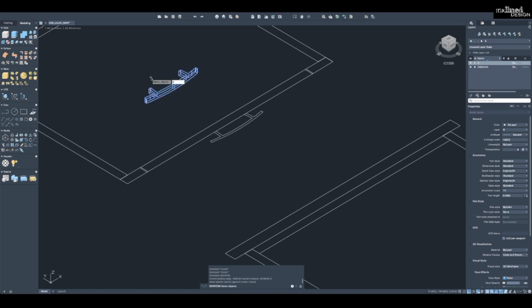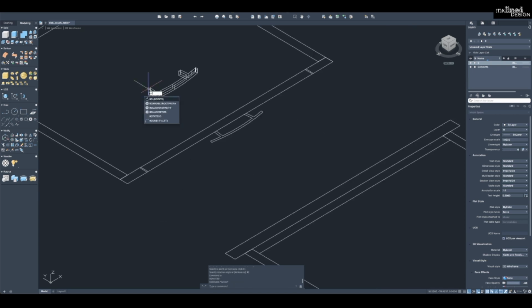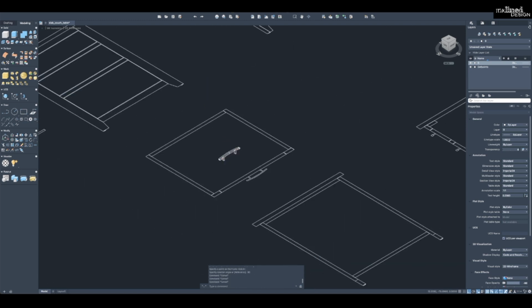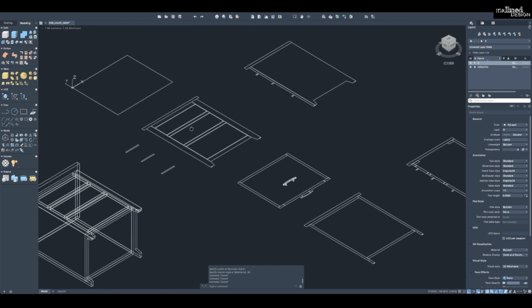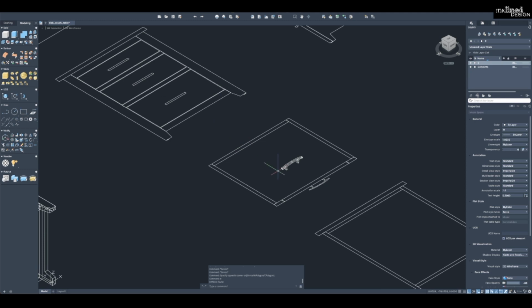We are going to rotate 3D and select the object. X, pick bottom of the handle, 90 degrees. Sorry, negative 90 degrees. Rotate 3D. Select X. There, minus 90. We'll rotate it up. Now, because I moved these handles off, but I do know they were in the center, what I'm going to do is just select these objects again. Center point, center. And now I have where my handles go.